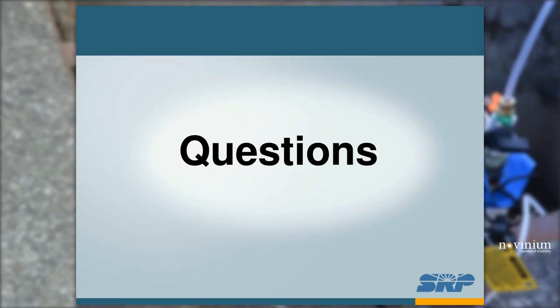Great, thank you. Our next question, how do cable types, soil conditions, and cable manufacturers influence cable faults? The only thing, again, that's one of the reasons why we look at installation vintage, is because typically within a given year, all those parameters are constant. The one thing that we can, again, as you would expect, our non-jacketed number 2 is our worst performer by far. We lose a lot of neutrals there, which increases the stress on the cable. We get deterioration of the outer semicon also on that cable.